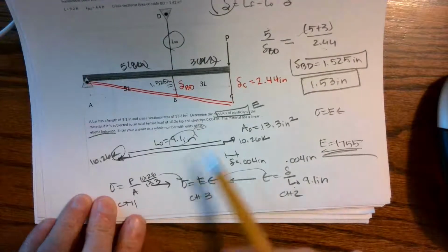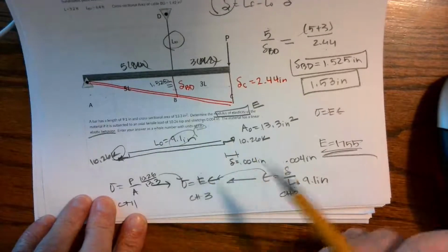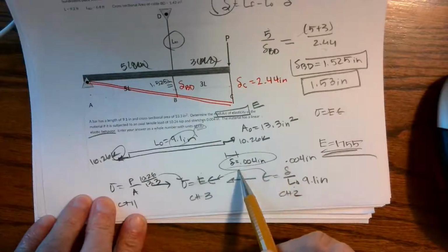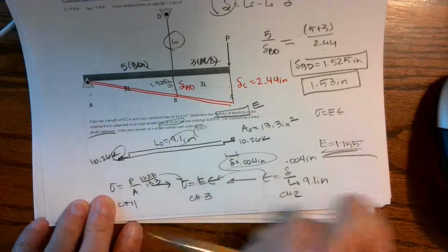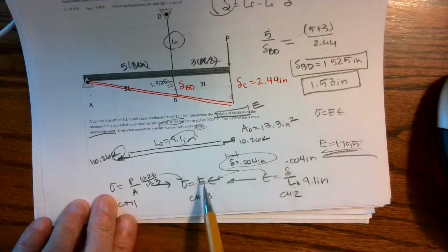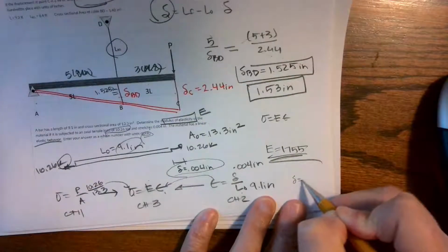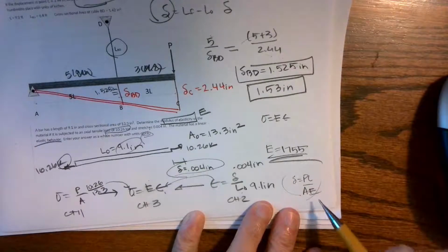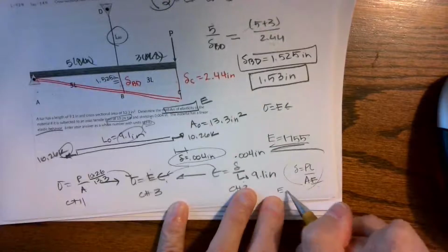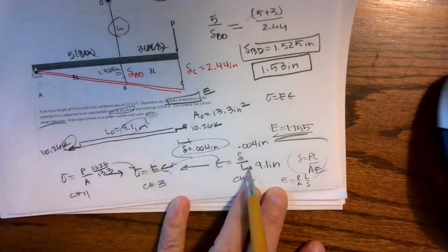It's just understanding what the definitions are. If I say the change in length, I have to know that change in length means delta. Okay? I have to know that a load is P. And I have to know how stress and strain are related. And now we actually could put it all together, and we know that delta equals PL over AE. And if I rewrote this, I would find that E equals P over A, length over delta, which is what I found here because I had to multiply by the reciprocal. Okay.